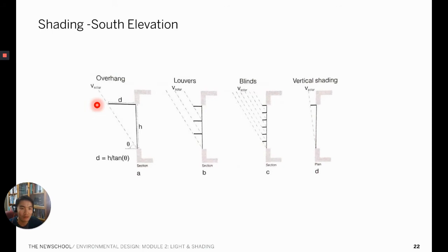When overhangs are higher on the wall and extend to a full shade line, they will still block the direct radiation, and yet a larger view of the sky is provided for the interior users. However, this would not be desirable in regions with significant diffuse radiation coming from many different directions. In this case, the use of shorter shading geometry while increasing the frequency of the shading geometry is better, despite some compromise of the clear view towards the outside.